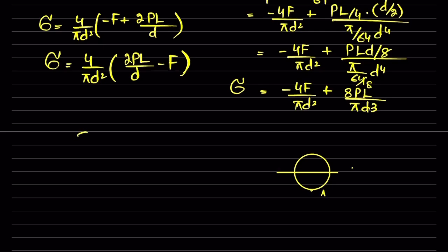So we know that shear stress is equal to V into QA divided by I into T. Here QA will be equal to Y dash bar into area. So this is the point A and there is no area over here. So QA will be equal to 0. So it means that shear stress will also be equal to 0.